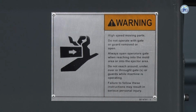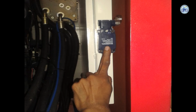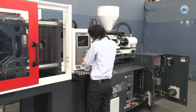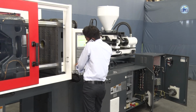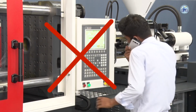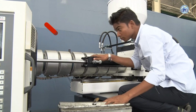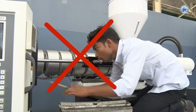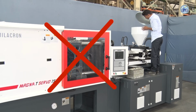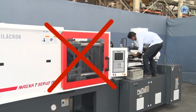Never remove or bypass the machine's mechanical, electrical or hydraulic safety devices, that is, safety gates, safety guards, safety switches, etc. Do not stand on any part of the machine and reach into the mold area while the machine is operating. Failure to follow these instructions may result in serious personal injury. Neckties, scarves, loose hanging clothing and jewelry such as watches, rings or necklaces must not be worn around moving machinery.